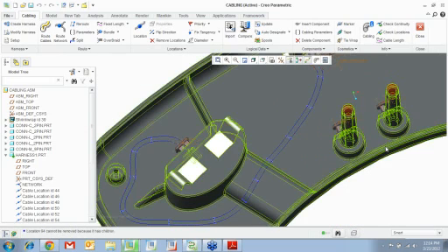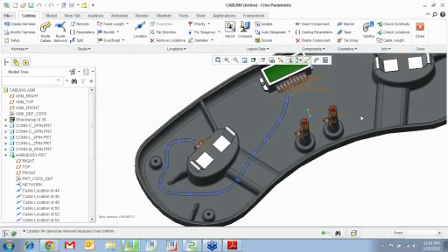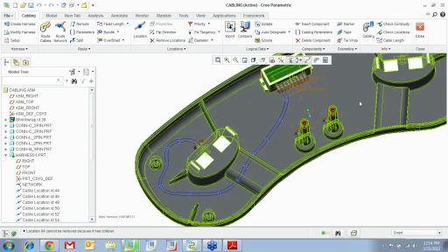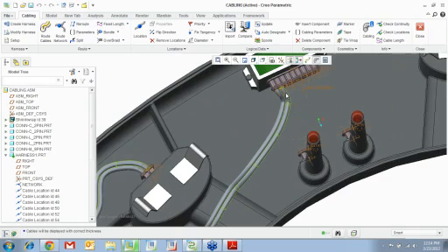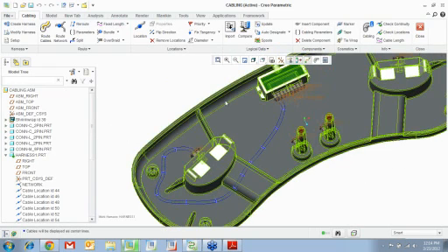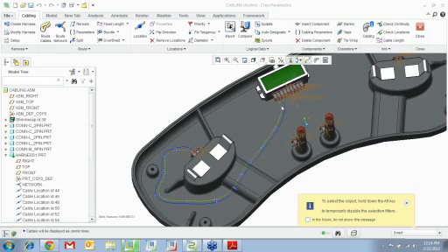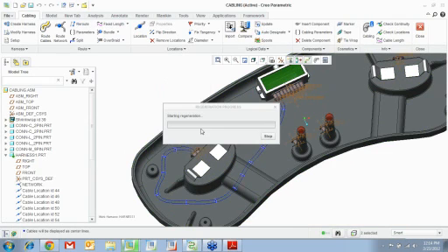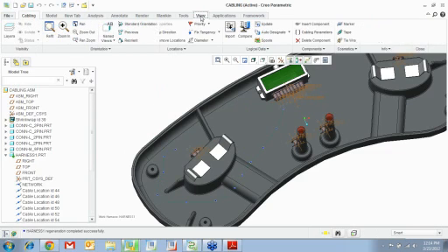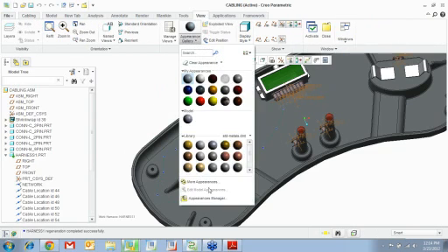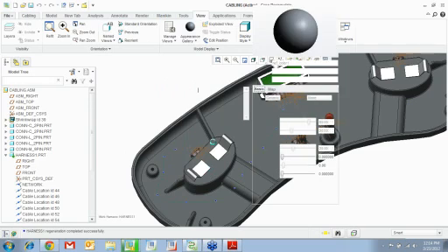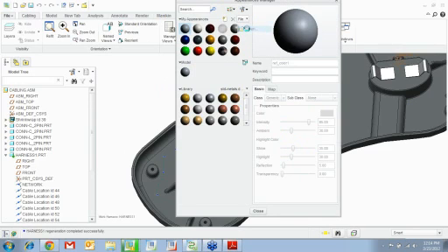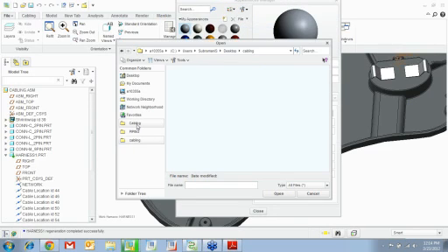Now I made a simple mistake right here. I did not add the color. So when I go thick line, see everything seems to be showing in like ash colored. So what I'm going to do is I'm going to pick them real quick, delete them, okay, because I can always recreate them real quick. I want to go ahead and add my wire colors. So appearance manager real quick, go to file, open, and then you want to go ahead and add your wire colors.